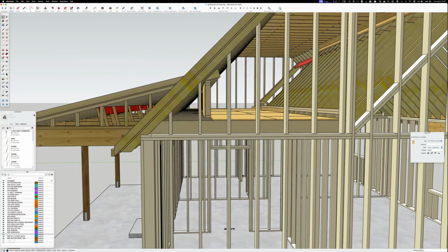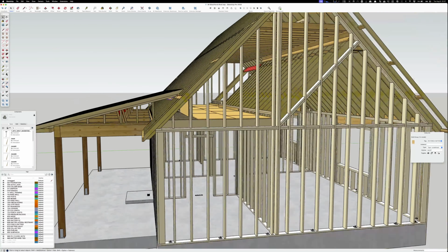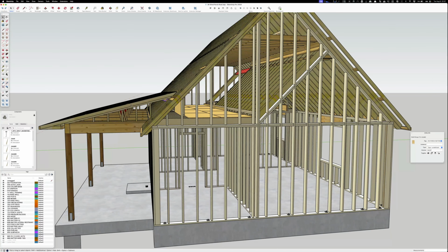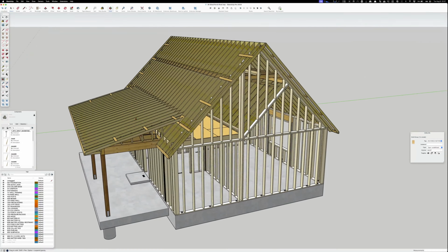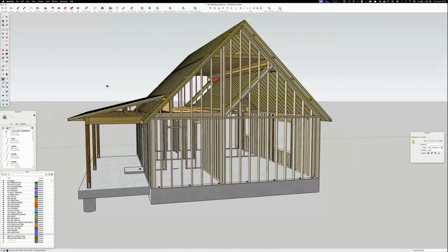And the only reason I put it here is because that's kind of a long span for a 2x6. If there's a 2x8, I think you get 11'7" for any pitch up to a 12 and 12 in a 30-pound snow load. And all that's in the code. I just know that that's the last one I did up in Linden.